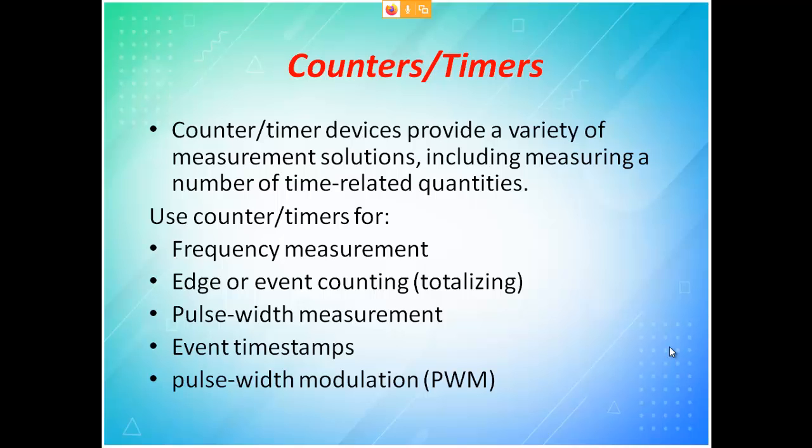If you want an example for a counter, the number of cars in a parking slot. A timer, for example, I have a washing machine, I am washing the clothes, so I will have a motor. Ask the motor to rotate in the clockwise direction for 15 minutes, then stop. Ask the motor to rotate in the reverse direction for 15 minutes. Now how are you going to calculate these 15 minutes? It is an internal clock. Here I will not wait for anything external, like one round is over, two rounds. It is only on a time basis, so we call it a timer. That is the difference between a counter and a timer.